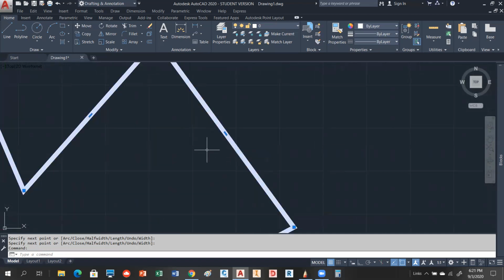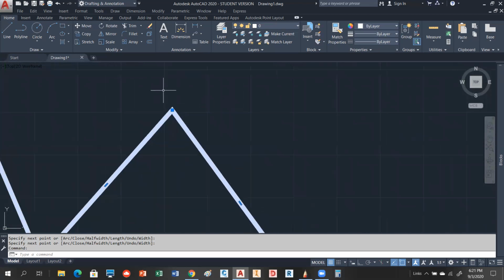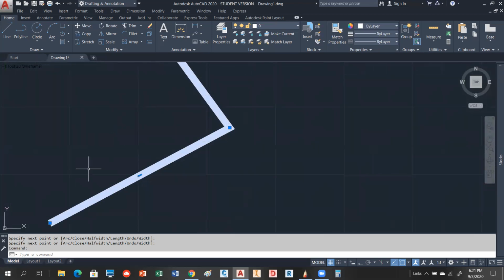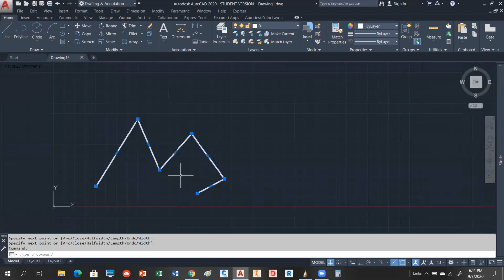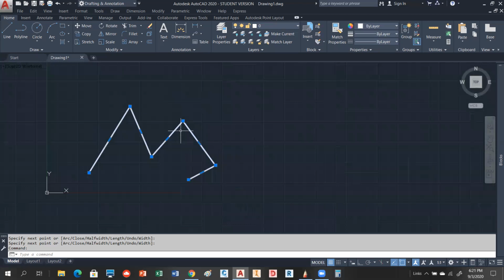So here's the other thing. If you click on your polyline, I want you to notice where the actual vertex is. It's embedded in the center. There's that, and there's that. And the other thing about it, it's always equidistant. In our case, it's 0.125 that way and 0.125 that way. So you can't have unequal widths with the width. It's always going to be an equidistant thing. That work for everybody? Yep.